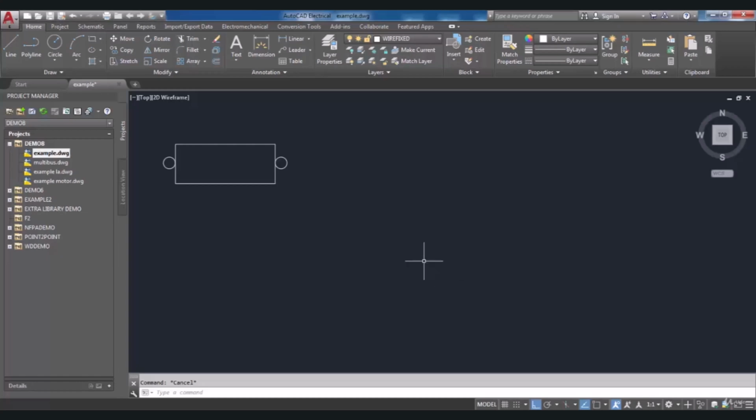As a designer in the field of electrical control panel designing, you may need to create new symbols that are not available in the schematic symbols menu. It is possible in AutoCAD Electrical to create new symbols based on your requirements. In this section, I'm going to give the procedure to add new symbols in the library.